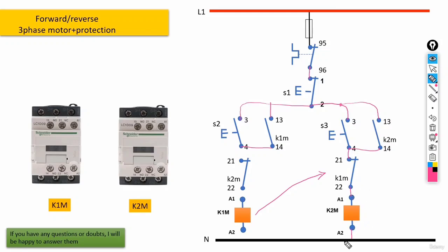Alright? Now guys, when the contactor starts working, when it gets activated, its normal closed contact that is now set here, as we said, would be opened. And this means that from now on, we cannot use this start push button here to convert our motor into a reverse motor. Okay? And well, guys, obviously the same thing is happening for the second contactor. I mean, we've set the normal close contacts of this contactor here in the path of this contactor, like this.